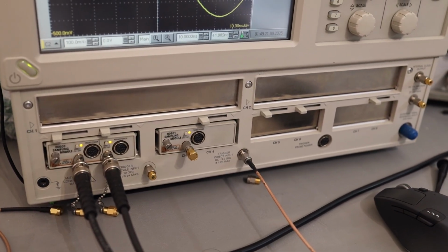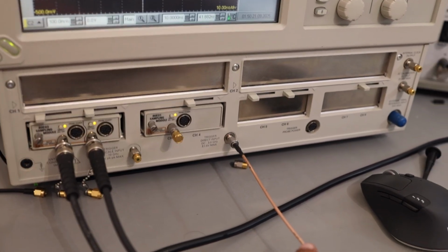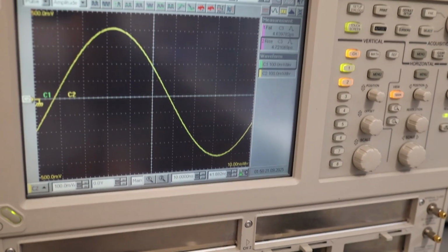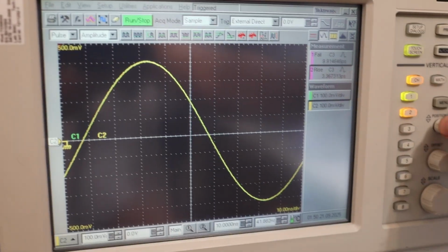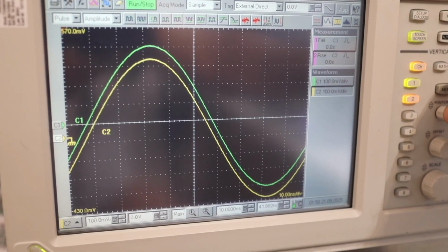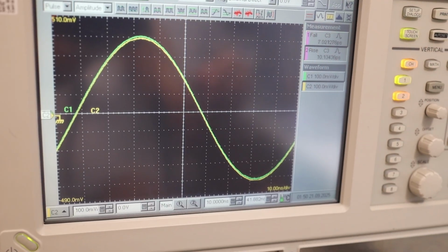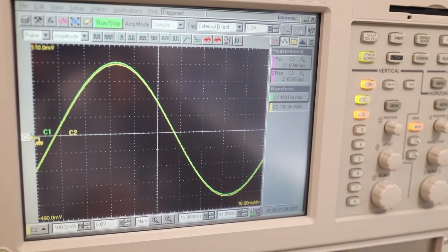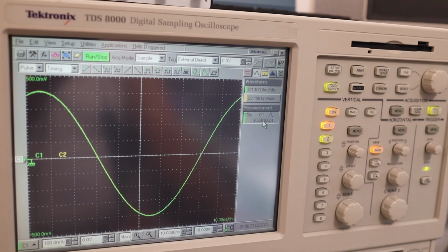Channel number 1 and channel number 3 are connected to the primary module, and channel number 2 is connected to the trigger, because this oscilloscope needs the trigger. And you can see both of the waveforms are very neatly overlapped on top of one another, and we will see if they have any kind of phase difference and what kind of phase relation they have between them. So let's get started. So I got my phase or delay measurement setup between both of the channels.